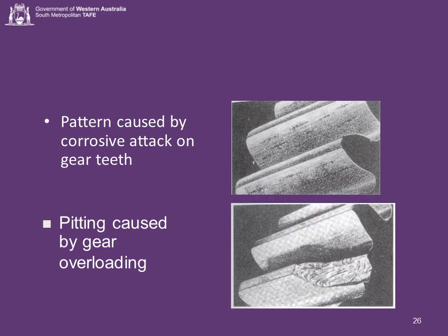Water and other foreign substances in the lubricating oil cause gear degradation and premature failure. The first picture illustrates a typical wear pattern on gears caused by water. The wear pattern generated by excessive gear loading varies, but all share similar components. The second picture illustrates pitting caused by excessive torsional loading. The pits are created by the imploding of lubricating oil.